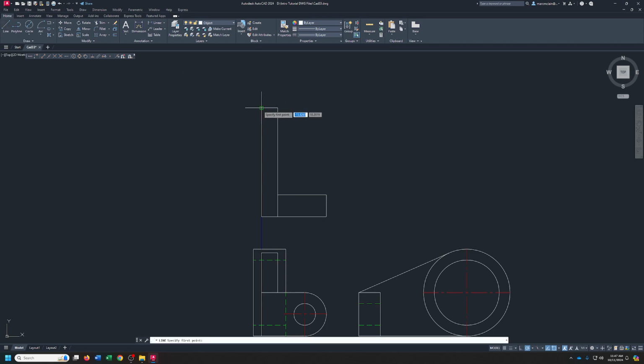So I know that I'm going to come down. Let's go out 0.375 and come down 2, and then come back to here. Now I'm going to delete that one. If I can hit the right key. Delete. There we go. So that's 2. We need it to be 4. So I'm going to grab this, pull this up. Tab, 4, enter. Now I've got a 4-inch line.